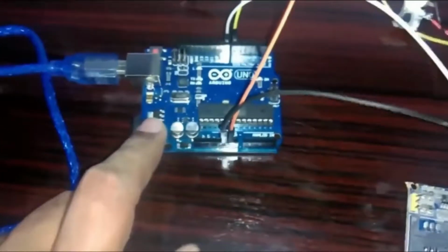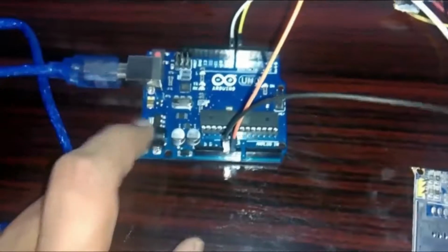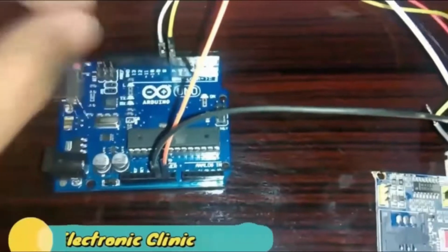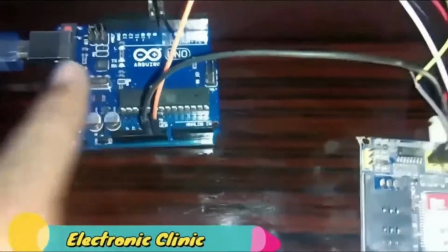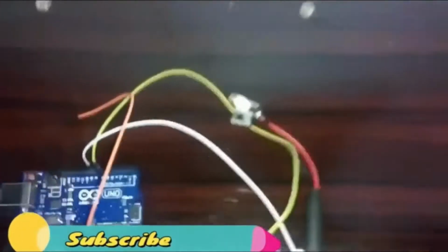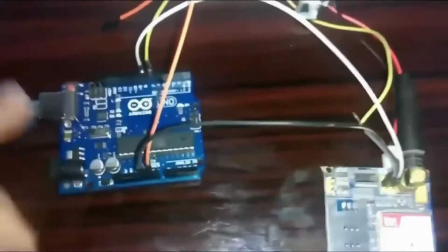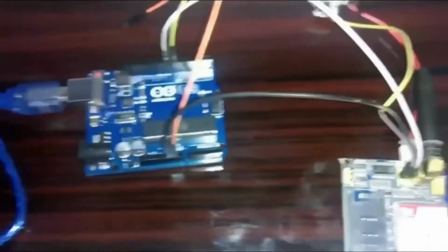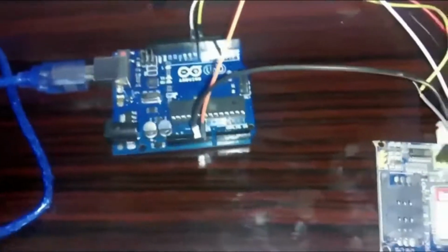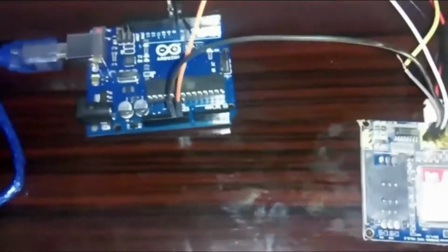So friends, you will also be needing an Arduino Uno. If you don't have the Arduino Uno, you can use Mega as well, but currently I have Arduino Uno, so that's why I'm using this one. In simple words, any program which is written for the Arduino Uno can be run on Mega, but the reverse may not apply, because in Mega we have so many input output pins, so there's a possibility that the program which we have written for the Mega may not run on the Arduino Uno. If we end up in a situation like this, then you will just simply change the pins in Arduino Uno, and then you are ready to go.